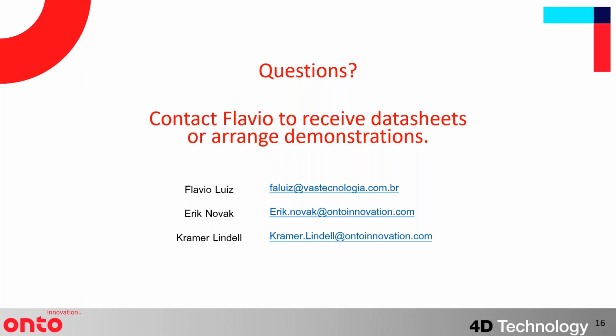So we would not recommend using those parameters to make determinations about your part, because you're more measuring our noise. But there are many surfaces, such as 3D printed material, cast iron, textured metal, and shot peened surfaces, all of which do fall within our noise floor.